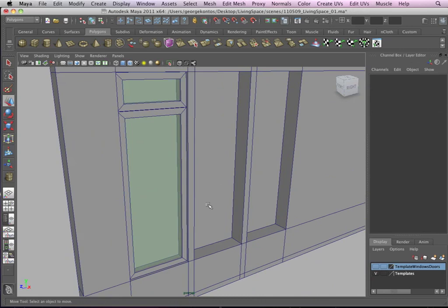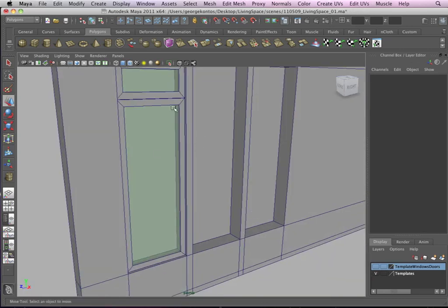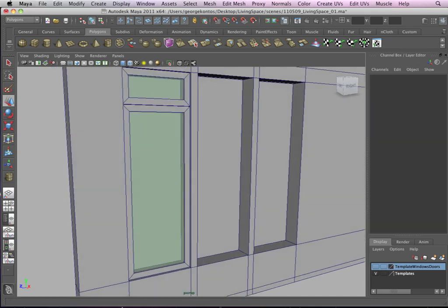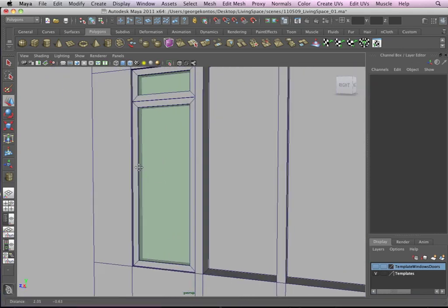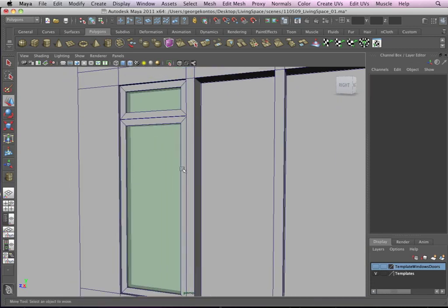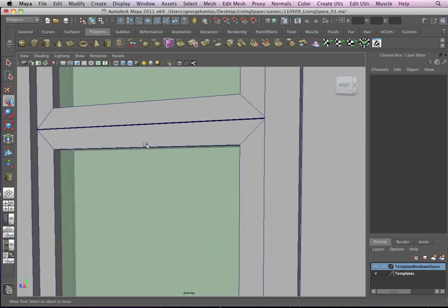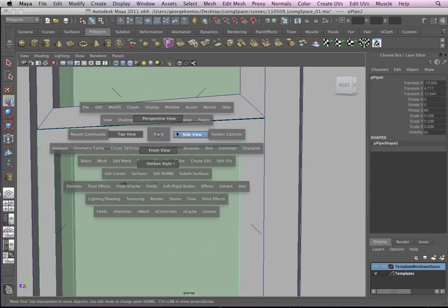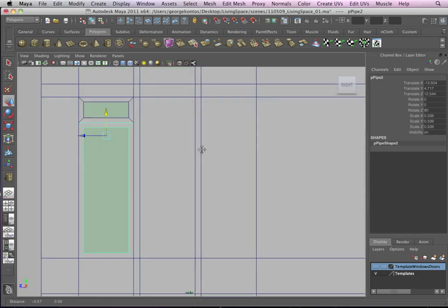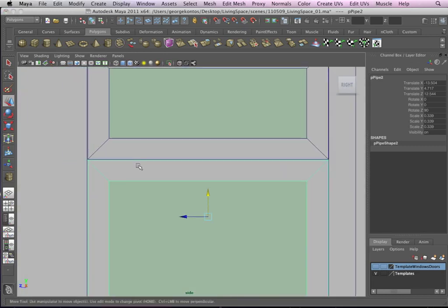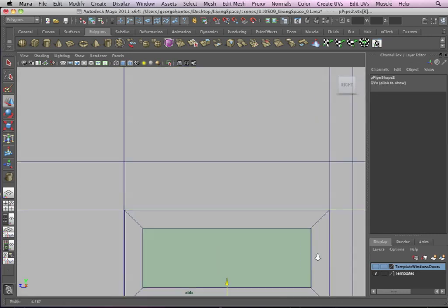I'm not done yet. I need some handles here, and how can we make a handle? We can use the curve tools, or we'll see. Let's look at some options in a minute, but before I go there, I'm going to also bevel the edges. I think we used bevel before. I don't remember. Have we used bevel? No? Okay. So let me make this a little bit closer here. Just fixing the frames a little bit.